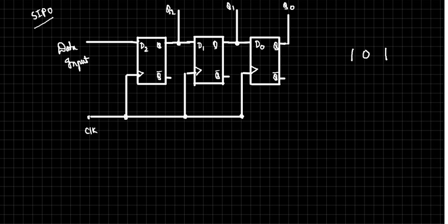That is the data I will feed here. Once the data has been transmitted, at that moment I want all of them to follow this fashion. So I will simply give the output of these registers to the LEDs. Simple, right? If you want all of them to operate in some predefined data fashion, then we can go for this serial in parallel out.